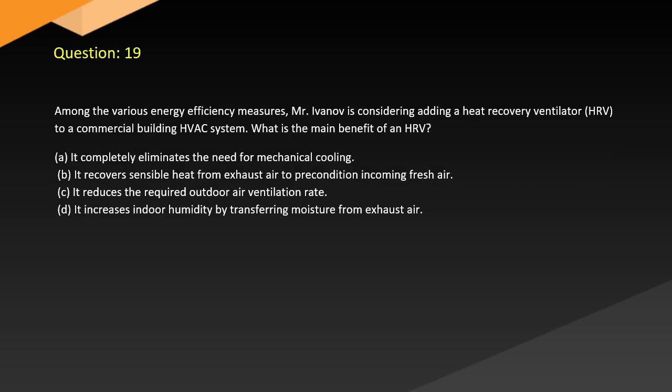Question 19. Among the various energy efficiency measures Ivanov is considering adding a heat recovery ventilator, HRV, to a commercial building HVAC system. What is the main benefit of a HRV? A. It completely eliminates the need for mechanical cooling. B. It recovers sensible heat from exhaust air to precondition incoming fresh air.